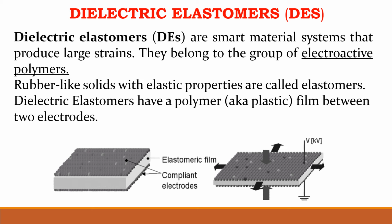Rubber-like solids with elastic properties are called elastomers. See, to a particular elastomer, I am applying two oppositely charged electrodes on the sides of that elastomer. And when I change the polarity of the electrodes, or if I alternate the current or voltage on that electrode, this elastomer undergoes either distortion, that means elongation or contraction, or it produces large strain. Such smart materials are called dielectric elastomers.